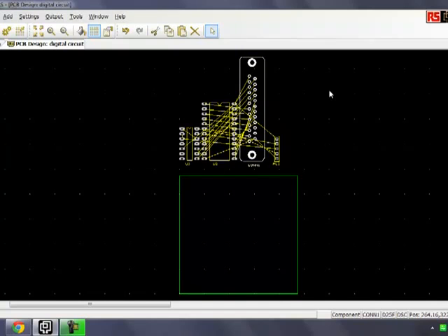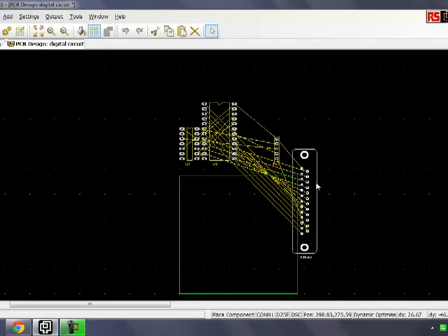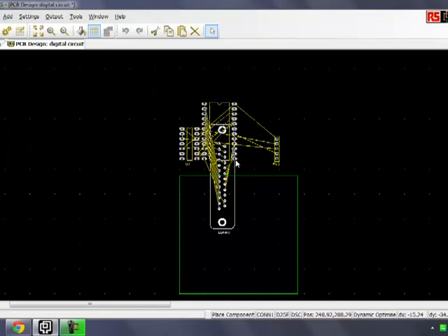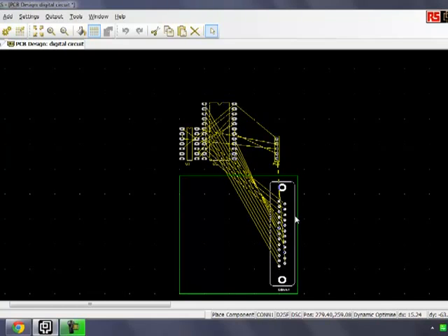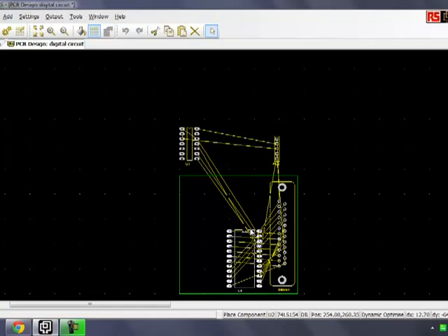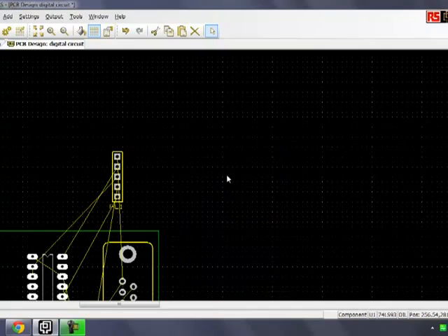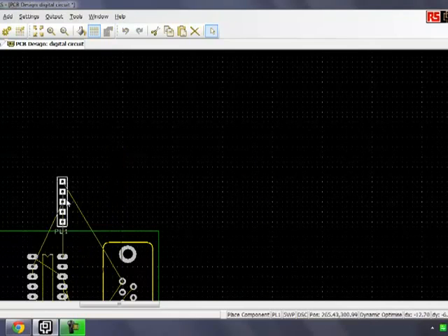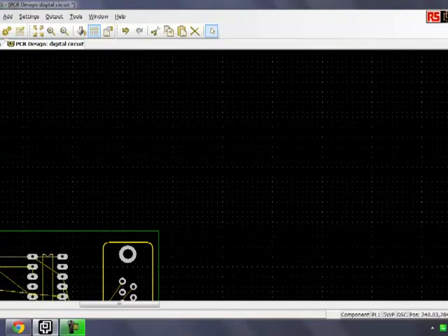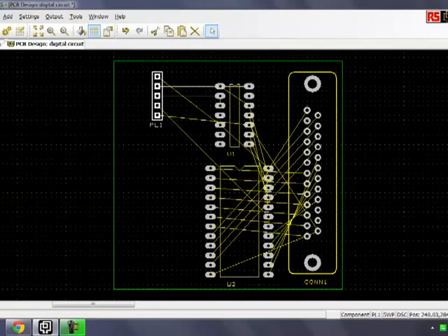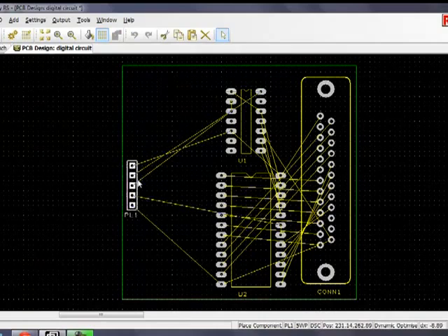So quite simply at this stage, what I can do here is pick up this connector, and you can see here that all the nets that we set up have been translated. What we can do now is bring these components down just by picking them up and dropping them. Oh, we just zoomed in on the screen, sorry there. Okay. We just press A, we remember, it's a shortcut command, it should take us to all. Here we can see the board now. I'll just move this down.